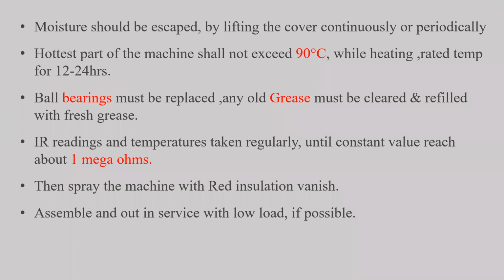Ball bearings must be replaced. Any old grease used has to be cleared, and we can refill with fresh grease. All the grease will be contaminated by the salt water, so it has to be cleared and replaced with fresh grease. Very important.